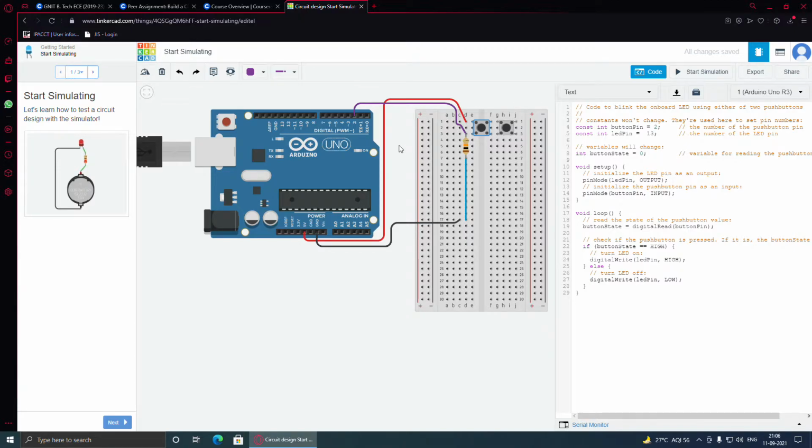So what resistance is being taken into account? Obviously the internal resistance of the component we are talking about. As we are saying, these components have a fairly low current rating, of the order of a few milliamperes, and standard voltages are like 5 volt or 12 volt. 5 volt or 12 volt is quite a high value for a component which has a current rating of a few milliamperes.